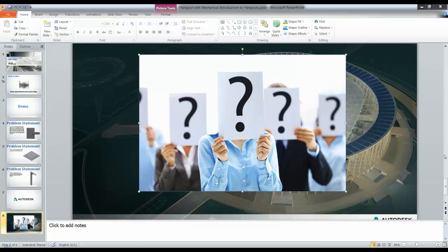So James is correct. This is Pat Tessero, I'm one of James' colleagues, and I've done an analysis similar to this where a customer was interested in simulating the welding process. What we did was a transient heat transfer analysis, where we simulated the intense heat following a trail around an object, and then performed a mechanical event simulation, MES analysis, using a nonlinear, temperature-dependent material.